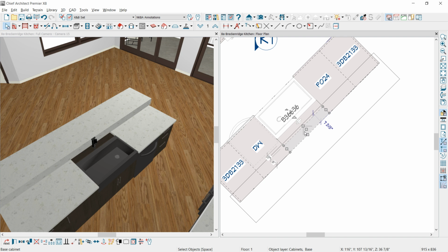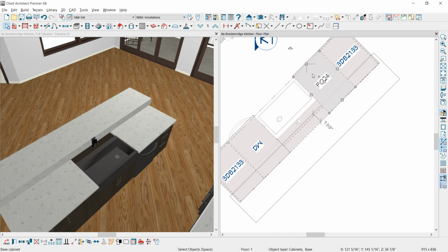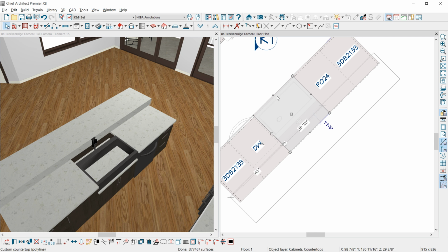One of the issues that I'm going to face is the larger countertop probably won't allow me to generate one automatically below it. So I'm just going to grab the cabinet off to the right, use this generate custom countertop in the lower left hand menu, and then I'm just going to pull that countertop over and use that, and then we'll stretch that to the right dimension and pull that back so that it's only over the other cabinet.